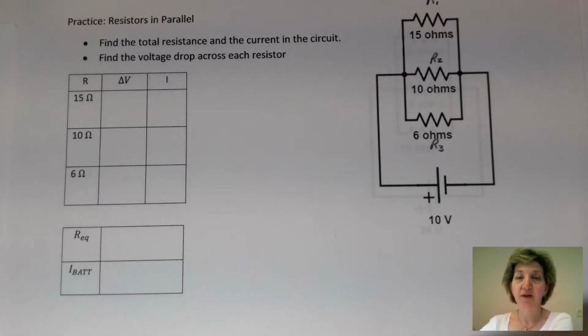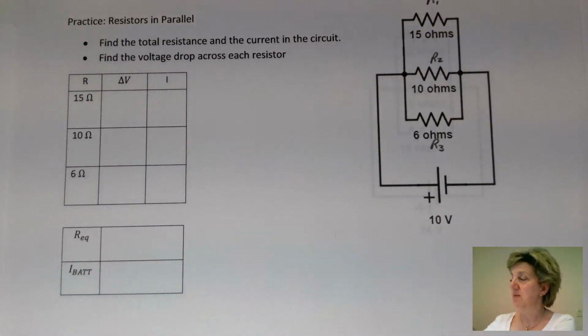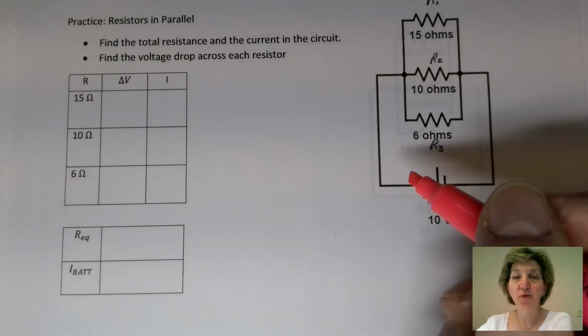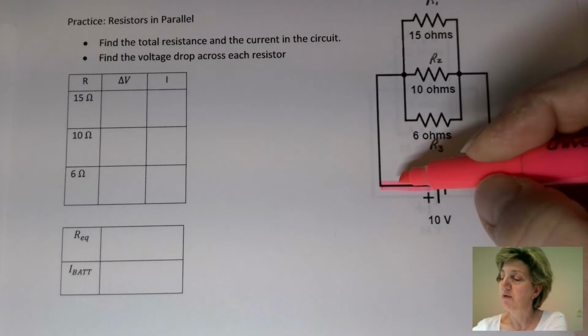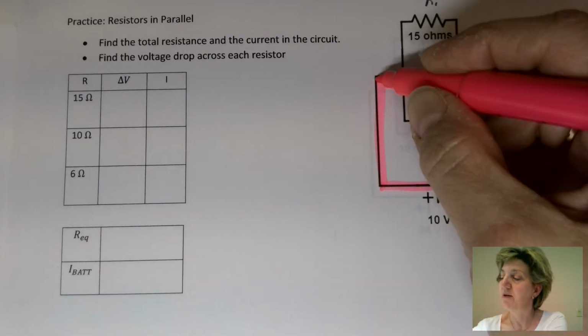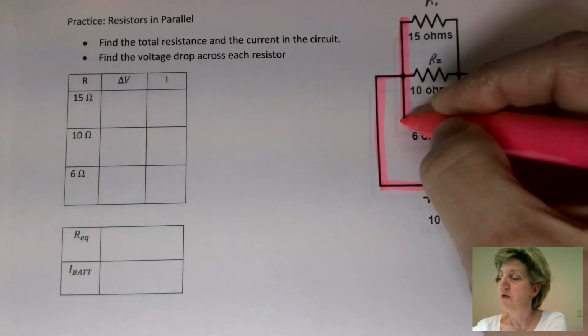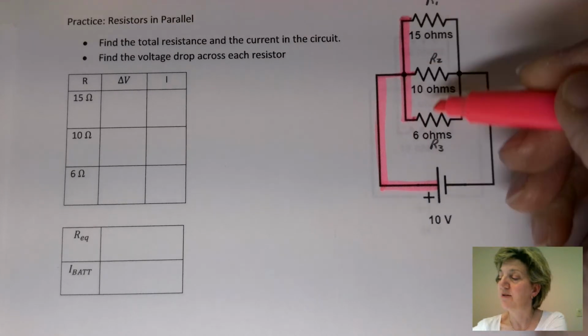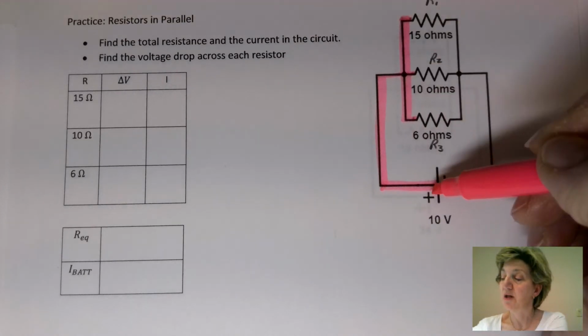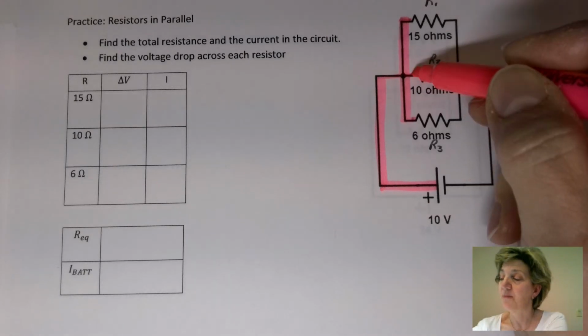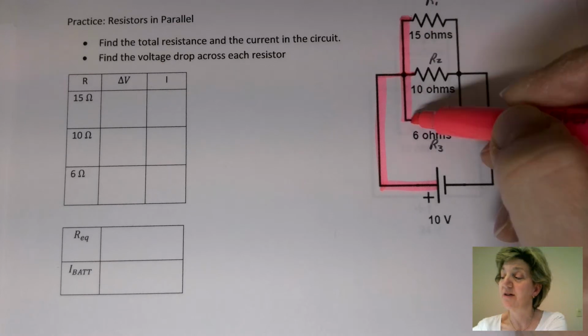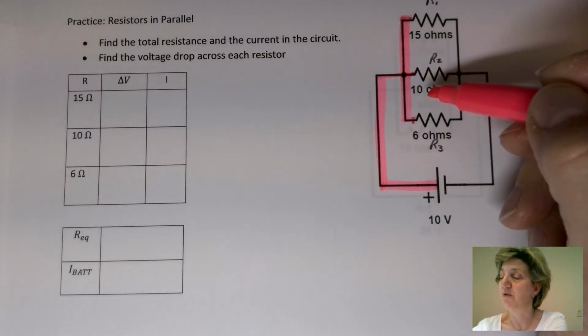As this video is going to show you, we're going to follow the same process to solve all of these simple circuits. Using our protocol for filling in with a highlighter or a colored pencil, we will go out of the high voltage end of the battery and highlight all wires that are connected to this high voltage, which tells you that this whole wire till this node and up to the resistor here, and up to that resistor, and up to that resistor are all at 10 volts.